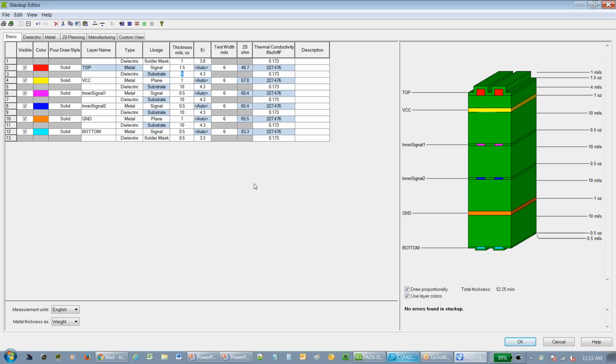For the simple stuff I'm talking about here that most people are doing, this would work great for a 6-layer board. But even on a 4-layer board, you may want to consider putting the power and ground planes closer to each other, because that induces a higher capacitance and therefore helps reduce any noise on your power planes, instead of using decoupling capacitors on a board.